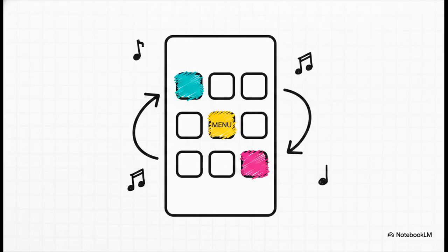When things get busy in the cockpit managing a missed approach, the last thing you want to do is fumble through menus. Just remember this rhythm for the standard flow, which we like to call the toggle dance. Menu, 1 left, 5 right. Just tap that out in your head and you're going to navigate the nav menu perfectly every single time.